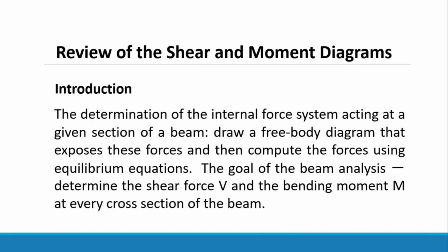And in our first lesson, we will review the shear and moment diagrams. Introduction: the determination of the internal force system acting at a given section of a beam. Draw a free body diagram that exposes these forces and then compute the forces using equilibrium equations. We will be dealing with summation of forces along y equal to 0, or summation of forces along x, which is also equal to 0, or summation of moment at a certain support or point equal to 0.